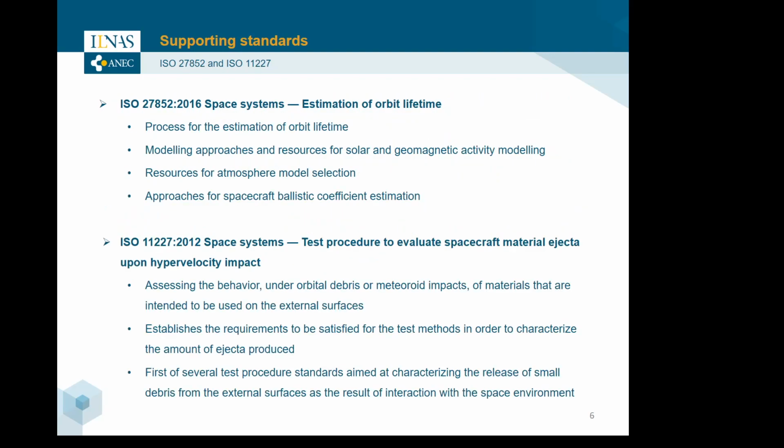Some more supporting standards with ISO 27852, which gives a process for the estimation of orbit lifetime, modeling approaches and resources for solar and geomagnetic activity modeling, resources for atmosphere model selection, and approaches for spacecraft ballistic coefficient estimation. These results from this orbit lifetime estimation can then be used to make sure it complies with the requirements of ISO 24113. This standard is also under review.